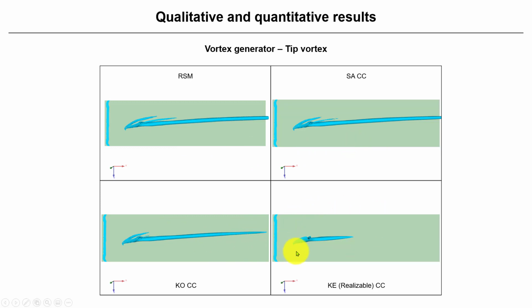And again, here the k-epsilon realizable is not giving good results. Okay, so in this case, it might not be the turbulence model of choice. And basically, I have to say all of the k-epsilon family models will not give satisfactory results here. Again, Spalart-Allmaras, very good behavior, a very economical model, specifically formulated for this kind of application.